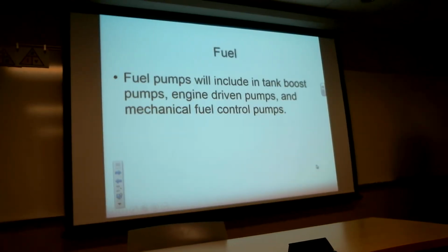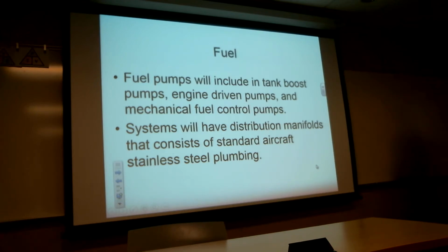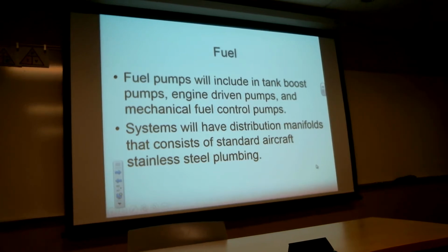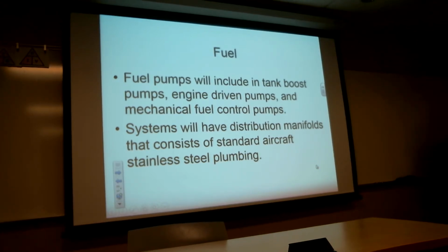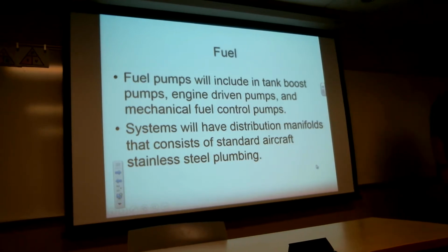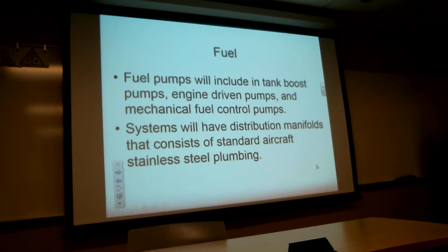Fuel pumps. You're going to have fuel pumps in the system, and probably strainers with those, because you don't want the junk and debris that's in the tank going through the fuel pumps. So you're going to have one in the fuel tank, usually to boost the fuel out of the tank. You'll have engine-driven pumps. Now these are delivery pumps. But then you're going to have mechanical and fuel control pumps.